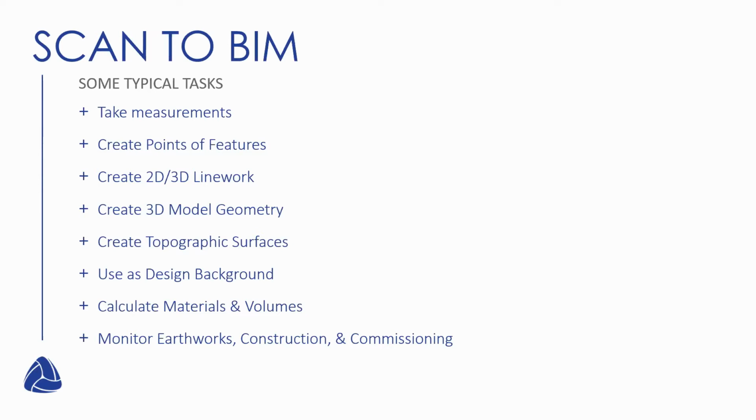If you perform scans at regular intervals along the lifespan of a project, you can compare certain phases to each other. For example, a scan while there's an excavation in place versus a scan where the road has already been built, or before the excavation has taken place. You can then use those different scans to generate surfaces and to calculate and monitor earthworks.